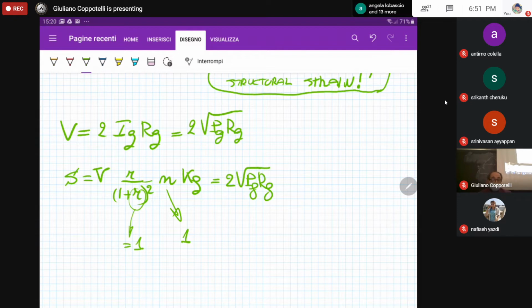So why have this second strain gauge? But from the operational point of view, we are having a strain gauge on leg number 1 that is feeling the strain. On leg number 2, we have the second strain gauge that is feeling just the temperature induced strain.